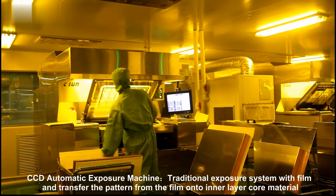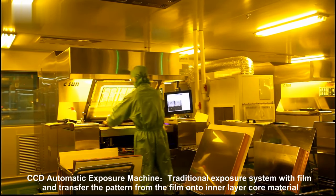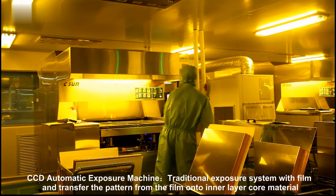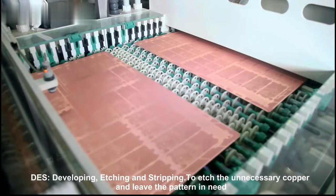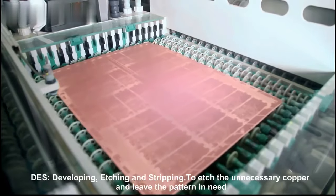CCD, automatic exposure machine. Traditional exposure system with film and transfer the pattern from the film onto inner layer core material. DES, developing, etching, and stripping. To etch the unnecessary copper and leave the pattern in need.